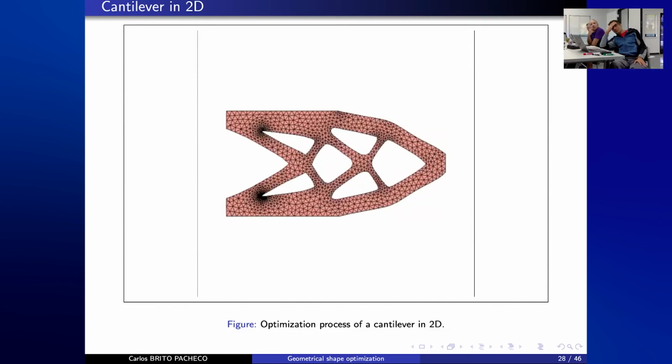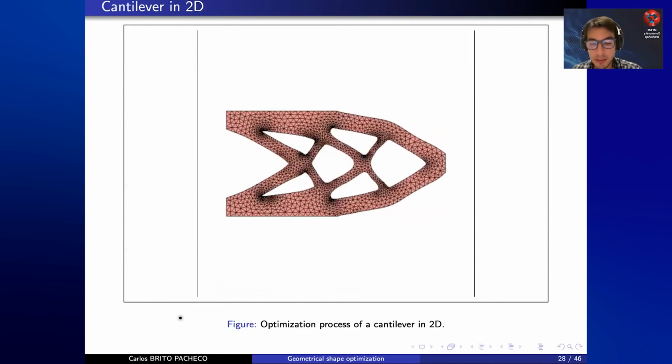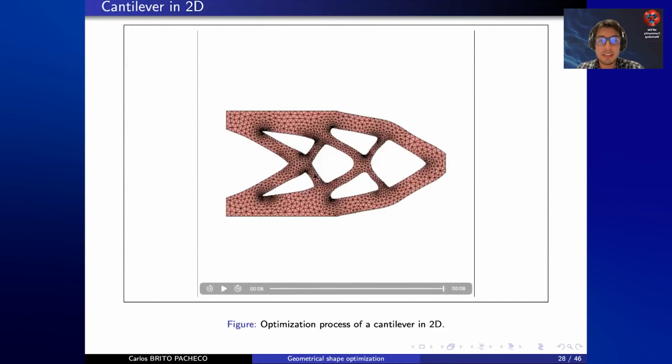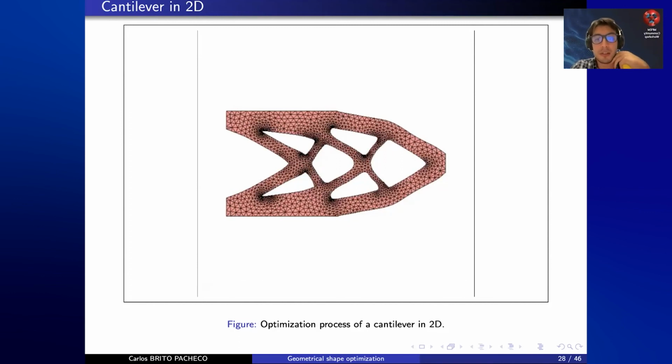And the distance function, what happens when you call that? The distance function is the level set function. I use this to represent the domain implicitly and track all the morphological changes. So the main advantage of this is that it can account for holes, or merging of holes, for example, versus just mesh displacement. If you were just displacing the mesh, you would soon get a broken mesh where you cannot do a conforming finite element resolution.